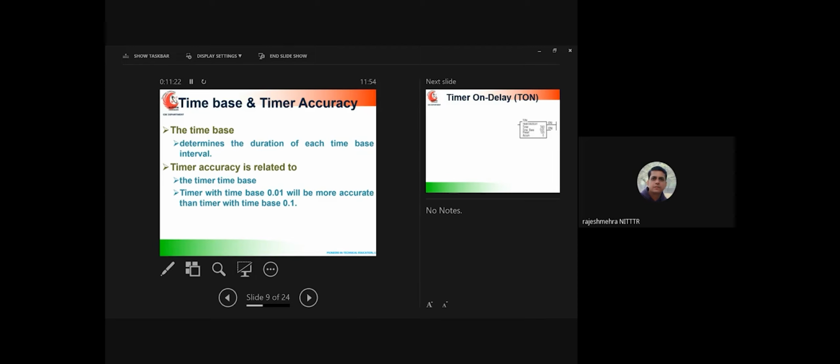If I select my preset value as 5, then my bottle will stop before reaching the filling station, because the actual time delay is 5.4. If I select preset value 6, in that case my bottle will pass the filling station and stop after crossing it. So basically my bottle will not stop where the filling station is. Accurately, it should be there below the filling station.